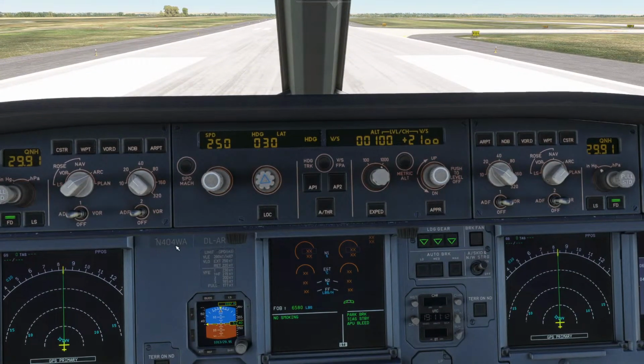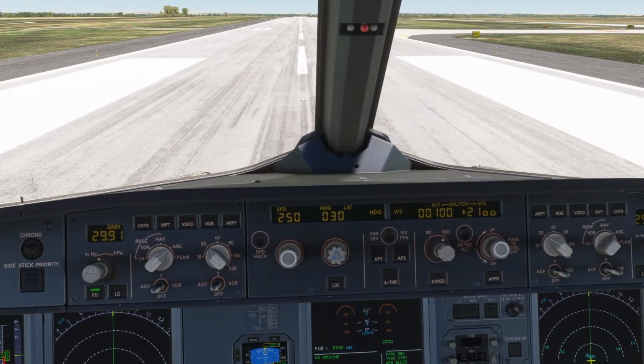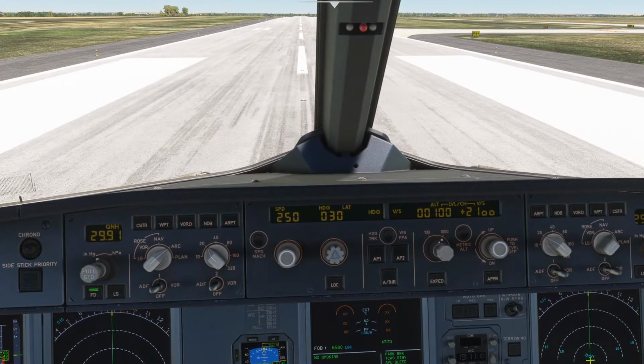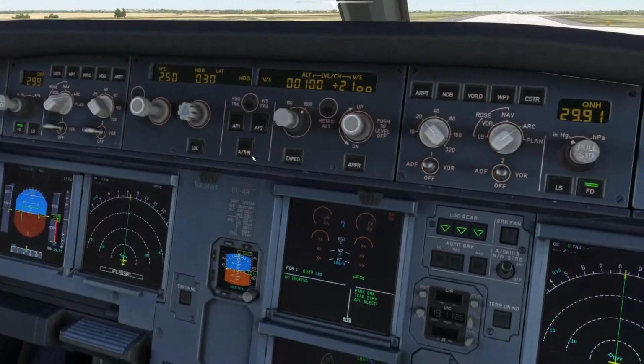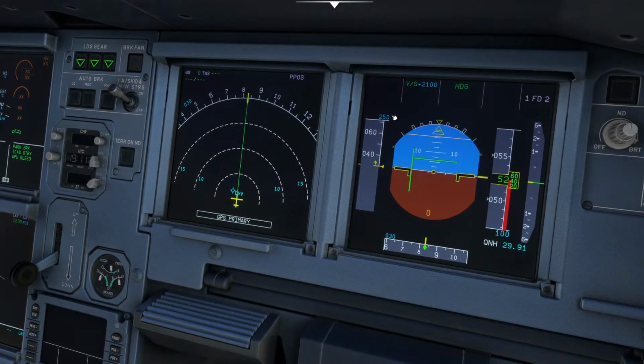It's always going to prioritize vertical speed, which I think is one of the things they talk about for climbing. Why is it hazardous to climb in vertical speed? Because if you forget, you can stall the airplane. So anyway, we're in open climb right now because we have 250 knots in the FMA